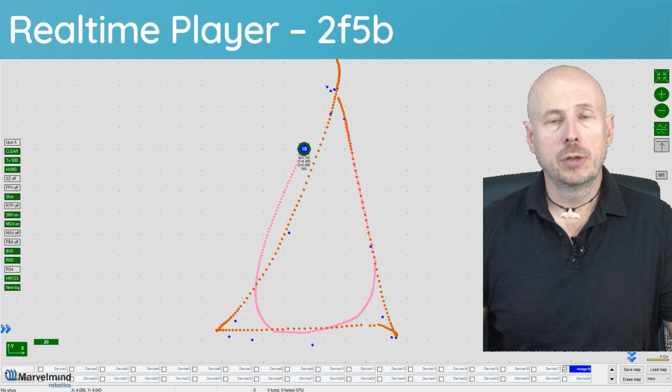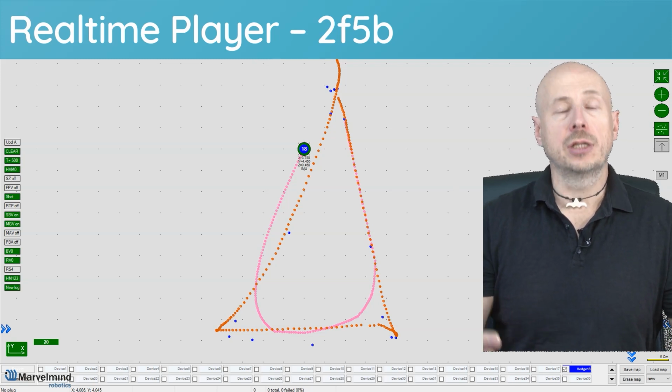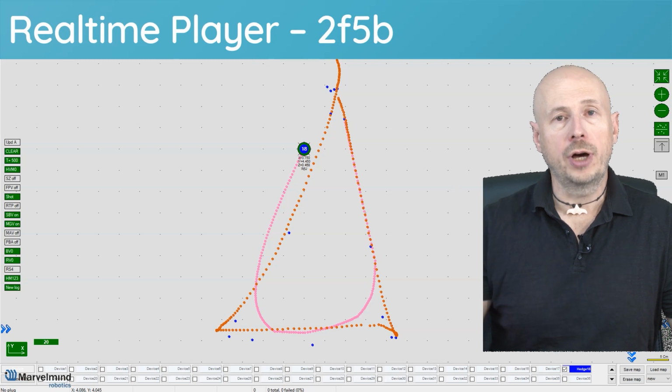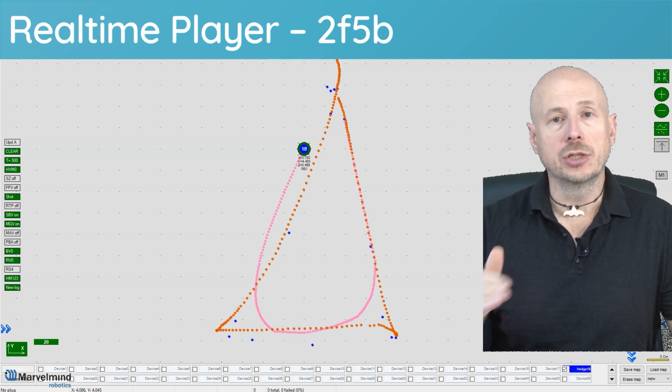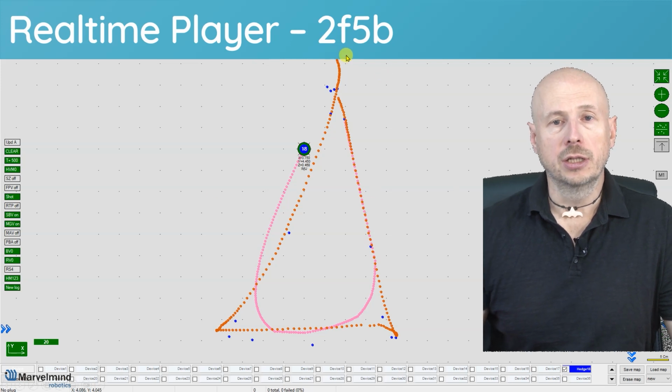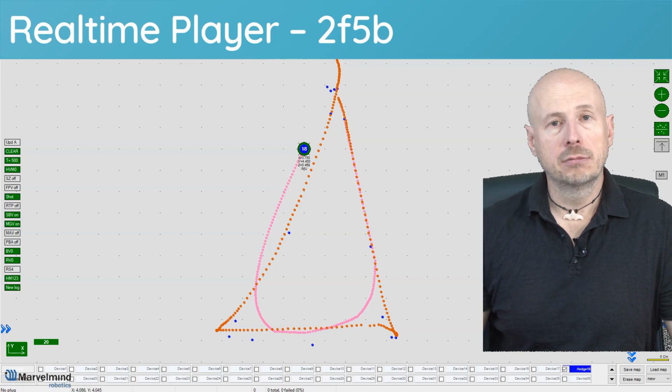Again, it's post-processing, so it's not real-time from our perspective, because our real-time is basically 10 milliseconds. But it's real-time, so you don't need to store the file and then play it. No, you can do this in real-time, but there will be latency. What latency? This is the latency. Effectively, your latency would be, in this case, 7 location update points. If you have 8 Hertz, the latency would be around 1 second, roughly 1 second.